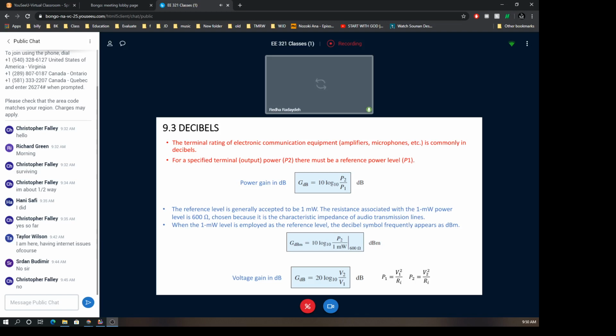So if you have an output voltage equal to 3 volts, and an input voltage peak value equal to 3 millivolt, we can express the AV gain first in decimal to be VO divided by V input, which will be 10 to the power 3 volt per volt.